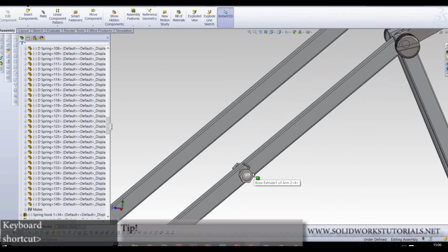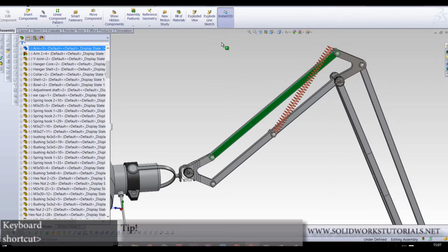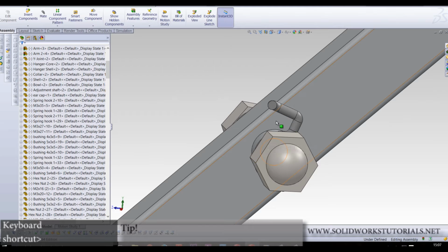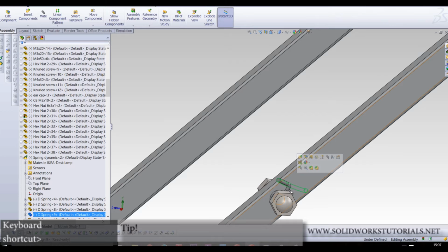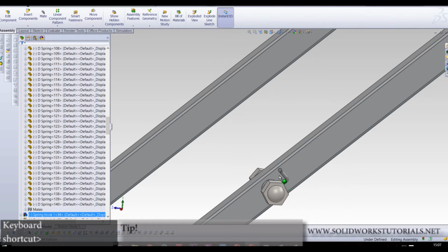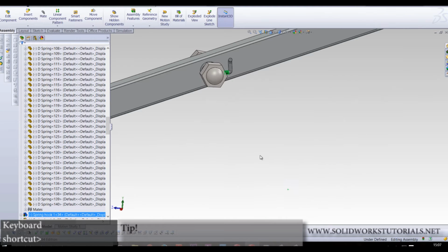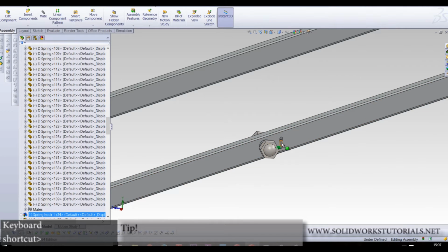See, even if I hover my mouse over it, you get some graphic failures. The solution I found was, if I try to move the assembly from the spring hooks, meaning if I just click on the spring hooks and try to drag them or turn them around a little bit, then it would work. As you can see right now, I can move it like this, really slow, and that's only with one spring set.